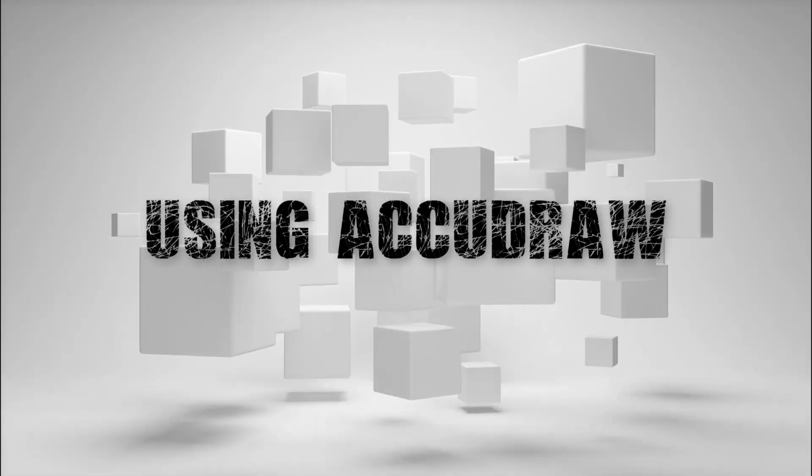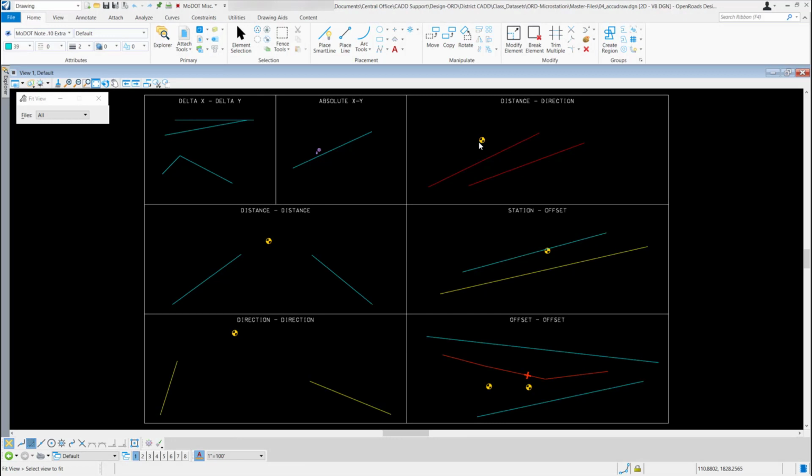Using Accudraw. First, let's go ahead and load up Accudraw. So I'm in my drawing workflow, I'm on my home tab, and in the primary group, this tool right here, if I click on the down arrow, this second option is toggle Accudraw. So I'll select that one to turn on my MicroStation Accudraw.